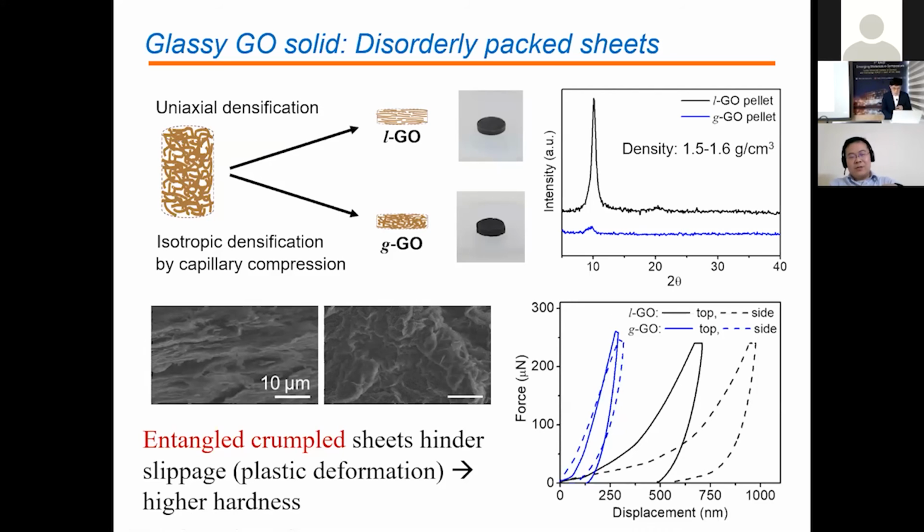So for storage, there's no problem as long as you don't dry it, or as long as you don't heat it, okay? Because heating triggers an irreversible change of graphene oxide. Even if you dry it up, you can still put water back. That's not an issue. But if you dry it up or accidentally introduce contamination like metal ions, that will mess up the redispersion property. That will also change the sliding behavior. Now for the carbon nanotube one, because cresol doesn't vaporize very easily, the boiling point is about 200 degrees Celsius, you could actually keep it easily for an extended period of time.